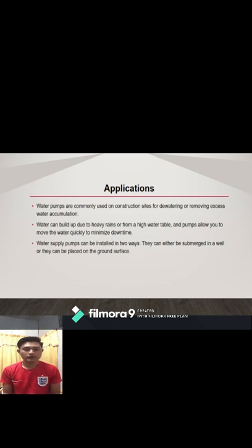The simplicity, versatility, and relatively low cost of this type of pump make them useful in many industries. They typically are used with relatively simple seals, so they are limited as to temperature and to relatively non-corrosive liquid. Because the bearings are located in the motor, close-coupled pumps are limited in size to about 40 to 50 HP for most applications.